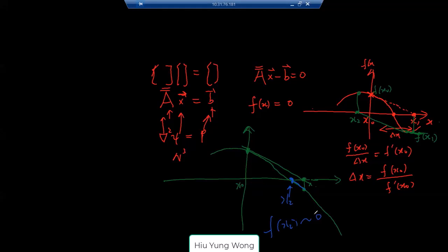That's the Newton's solution. Newton's method iteration, right? So when we say iteration equal 100, we allow it to iterate for 100 times. After 100 times, if you still cannot find the solution, I say it does not converge. The simulation failed. For example, if you are unlucky to have this curve, then you cannot find the solution. But usually you can find the solution. Is this clear to you?